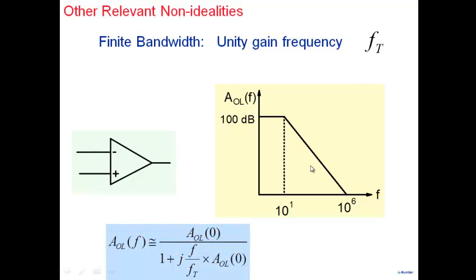And so if you want to know how your op-amp behaves, a very simple picture of an op-amp is that the op-amp's gain is a function of frequency, which is given by this very simple first order transfer function here. A_L0 is the gain at lower frequencies, and it falls as 1 by (1 + jf/f_3dB). That's it. And f_3dB is written as FT by A_L0. So that's how your op-amp actually looks. It's a high gain amplifier, but only at lower frequencies. And as you go to higher frequencies, the gain falls.